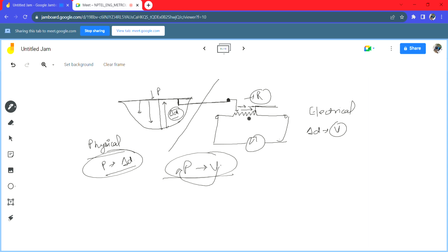And for similar sections, like of a C tube, if we apply pressure here and it is fixed, and this free end is connected to a potentiometer, the more pressure you apply, the more it bends. The more it bends, the farther it moves. And we get different resistances for different pressures.